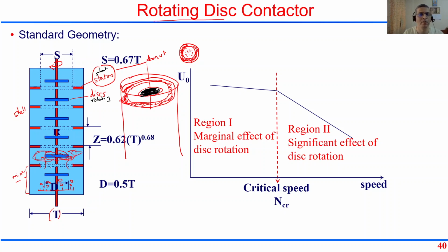Again it gets broken up further. Mass transfer occurs. The drops go to the next stage through this gap. Again mixing happens. Again it goes to the next step. Again mixing happens. Again it goes to the next, and so on. So the organic phase, let's say, is put in continuously. This phenomenon of droplets coming, getting mixed, going from stage to stage, and then going out from the top. The aqueous phase that we put in goes to the first topmost stage.